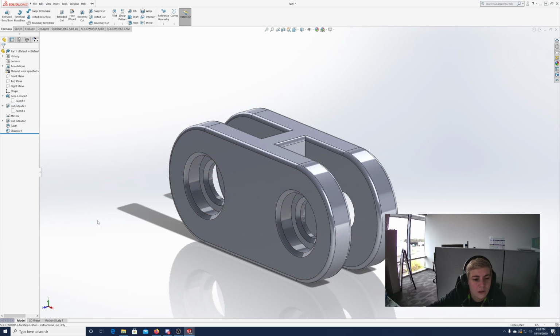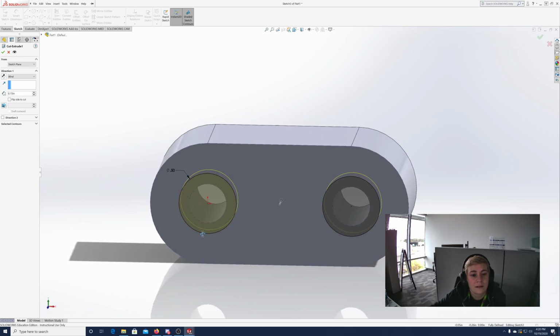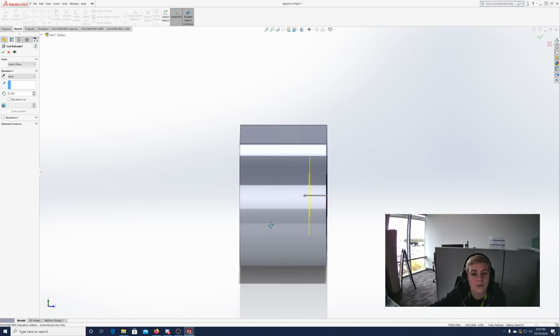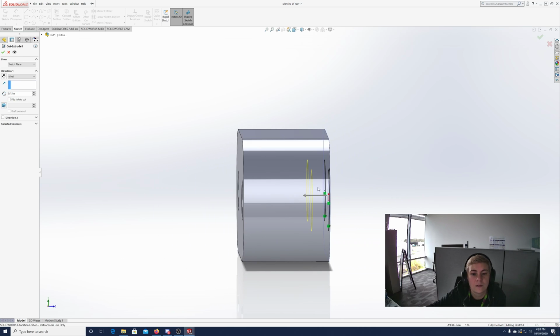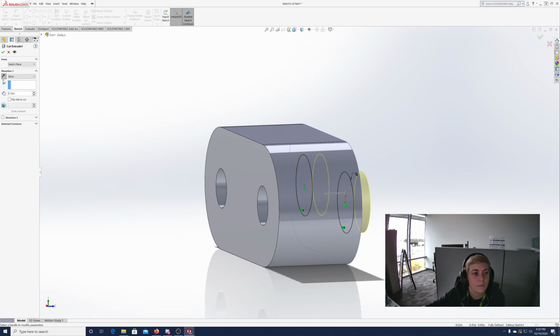Make sure that everything in that looks like the book. So if you go to edit that, make sure that all of these options here are the same as what's in the book. Make sure that your counterbores are actually going in and not out. So see how when I turn it sideways, I can see those little yellow circles inside the shape? You want those. So if you get it backwards, they're going to be wrong. Okay, cool.